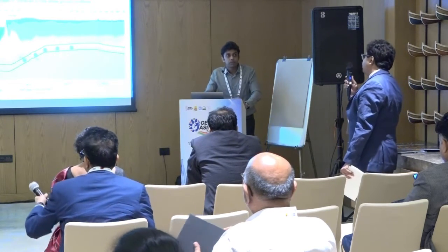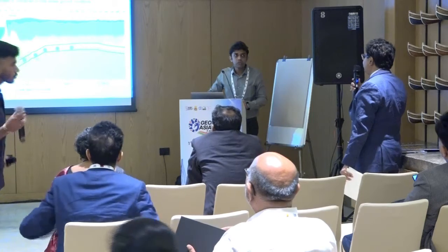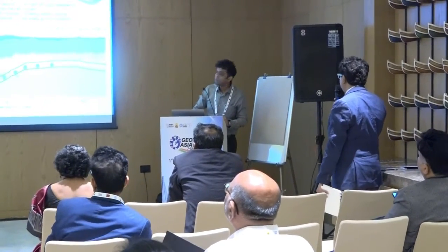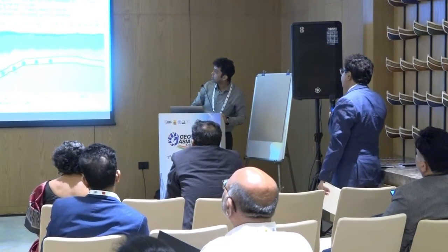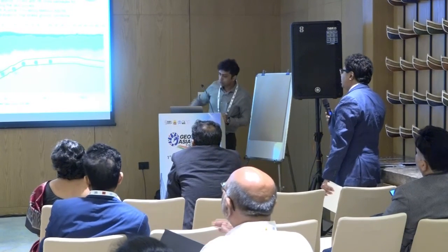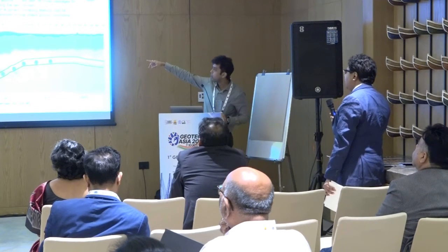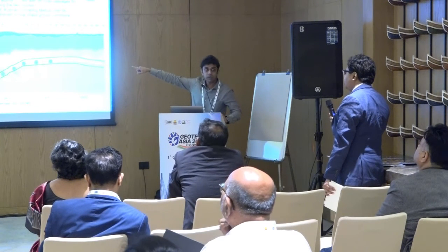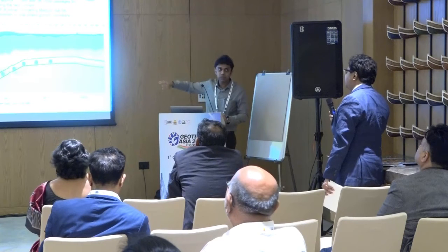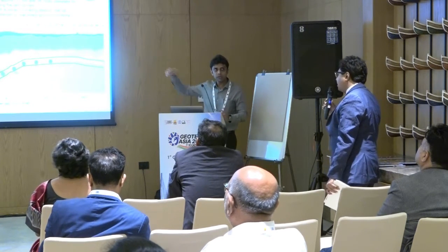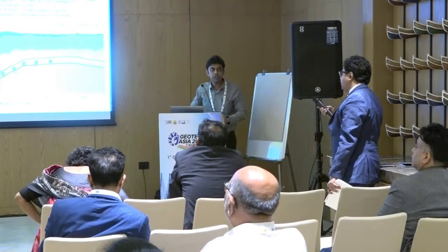Just one quick query. Your CP1 and CP2 depth starts from 5 meters, whereas the ground improvement starts from 10 meters. No, sir, this is shown in meters MSL. The ground level is at 5 meters, and the top of the tunnel is at -5 meters, so overall it becomes 10 meters. I have not put it as meters below ground level; I have put it in RL, so that's why.